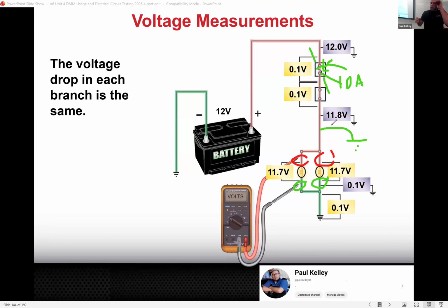But if you understand electricity, there are laws, it follows laws, the numbers don't lie. It can't be different on this car. It helps keep us all in line so that we all understand your numbers tell the story. So you can't say, well, I got this measurement, but on this car it was different because the electricity wasn't feeling good that day. So we do cover the laws, but the main voltage, available voltage or voltage drop tells you everything you need to know, like 99% of the time.